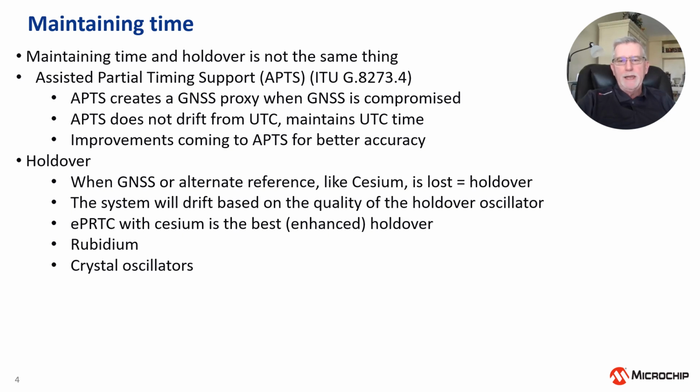We can provide enhanced holdover that is phenomenal, where we can hold a few nanoseconds for several days or even weeks. And we can achieve incredible performance where we can hold less than 100 nanoseconds for 30 or 40 days or even more. So holdover components are important to understand based on what your requirements are.